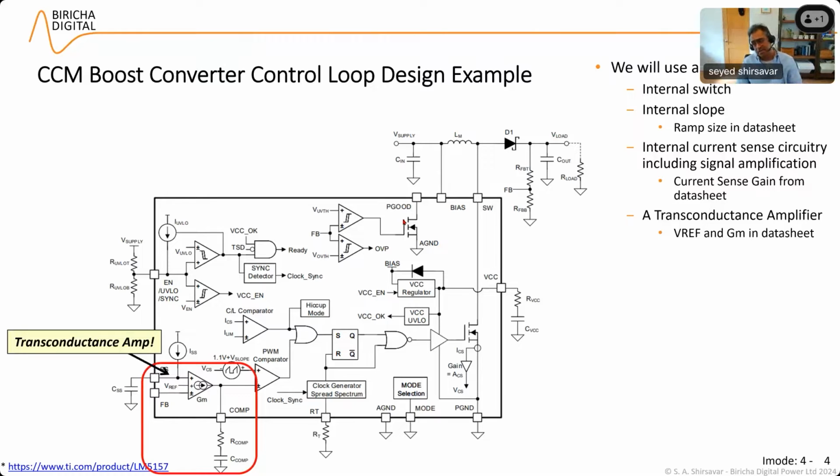It is normally very, very easy to quickly look at a schematic, even not the data sheet of a power supply, and say whether it is a normal op-amp or a transconductance op-amp. All you have to do is look at the comp pin, the compensator components, and if they're tied to ground instead of being fed back into the input side of the op-amp, then it's a transconductance amplifier. The amplifier is usually drawn like this with a current source in it and an arrow, so it's 2 circles and an arrow, and sometimes also put GM on it to show that it's a transconductance amp. GM is of course the value that they quote in the data sheet, which is the transconductance of the amplifier, and we're going to talk about that in just a little bit.